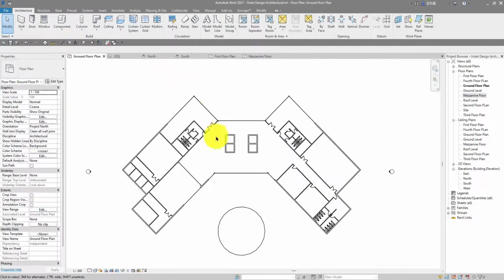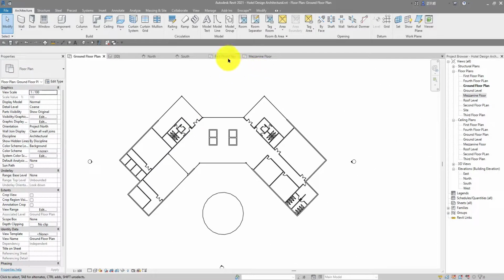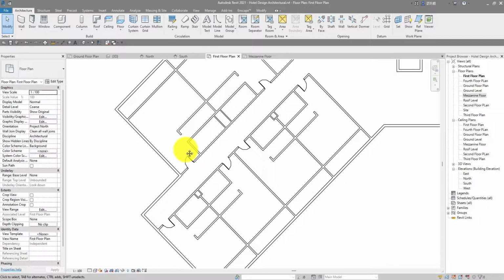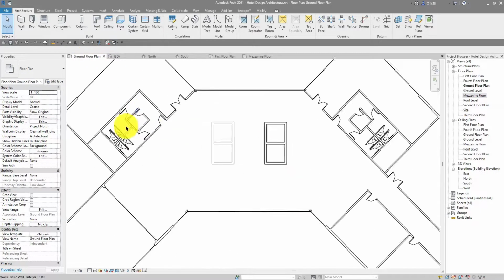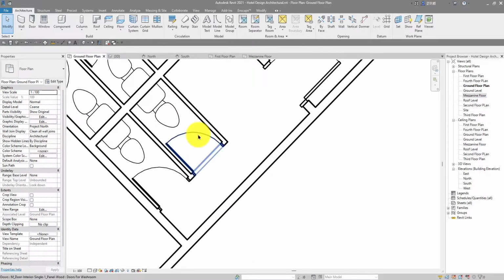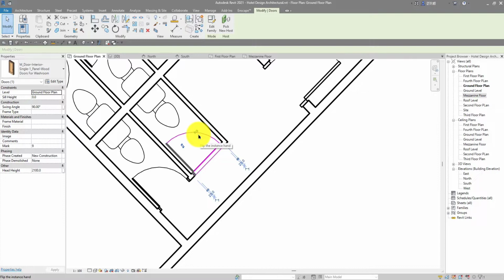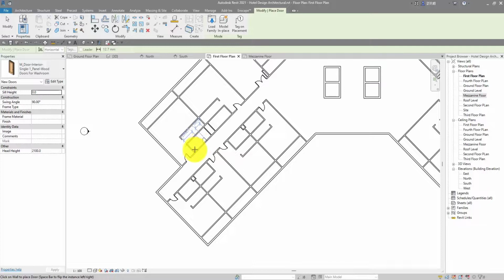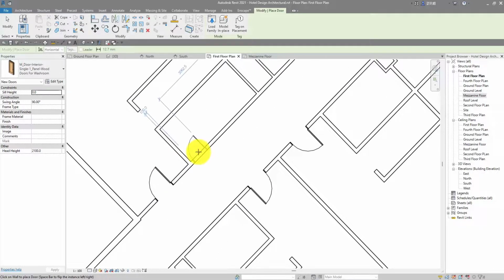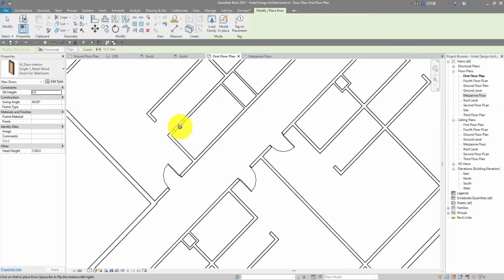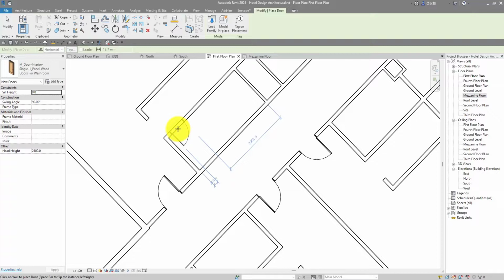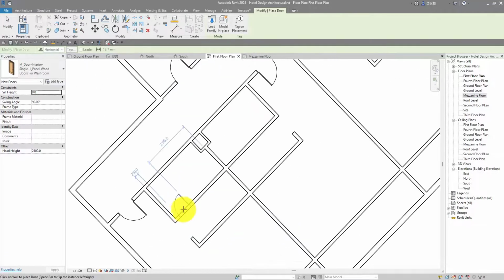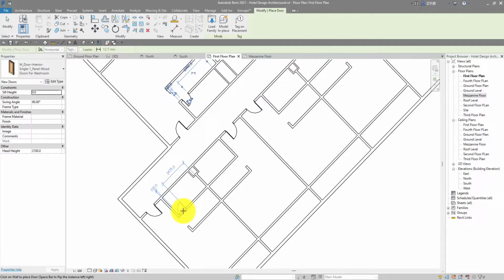So let's go back into the ground floor plan. The first floor, all right. We would want to place in a door for our washroom, all right. I want us to use one of these doors in here, all right. Let's just use one of these doors. So just create similar, get into the first floor, all right. When you just create similar, you can just move into your first floor tab, and then you just leave about 200 and place that door in there. And you'd want to do the same thing for this side as well.